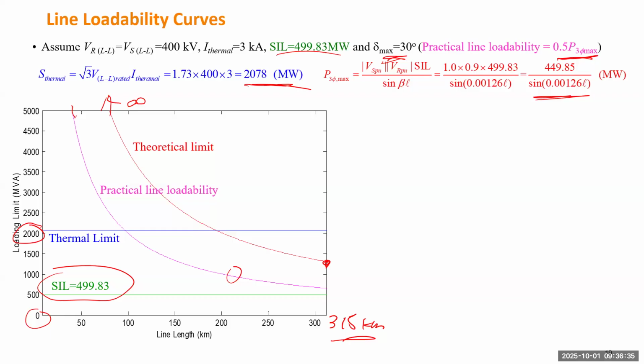So now you can see the relationship. The surge impedance load is actually the ideal load. If you operate the line delivering power exactly equal to the surge impedance load, you have the minimal operation challenge. The voltage everywhere will be the same, and the power factor along the line will be the same. That's the ideal load. But usually our load can be higher than the surge impedance load.